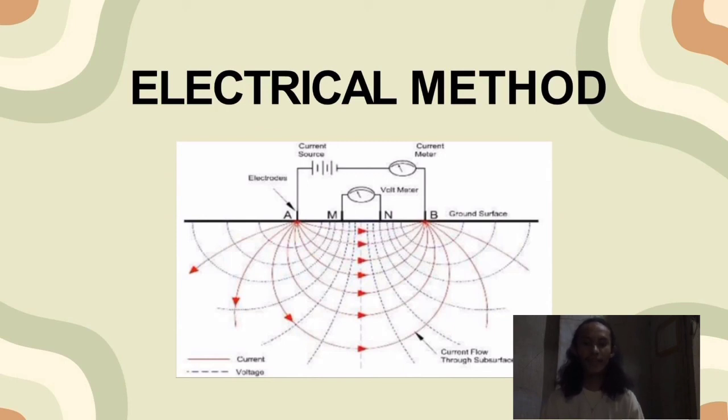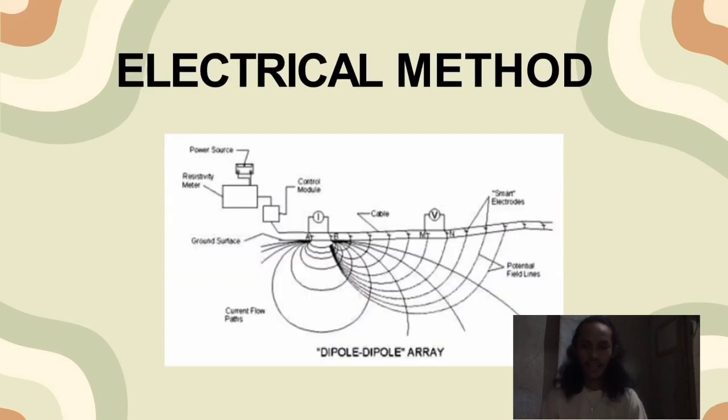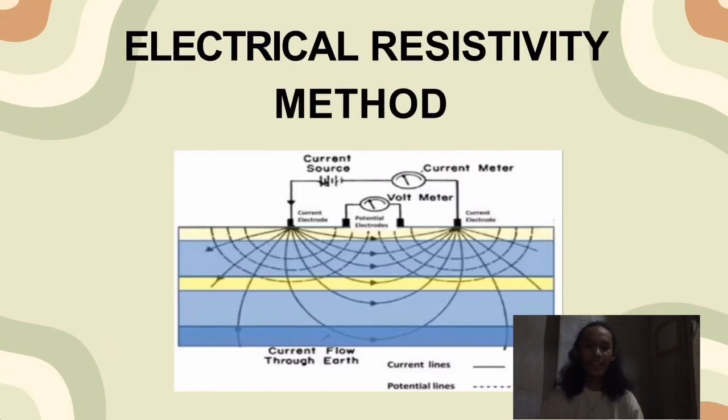Electrical methods are numerous and more versatile. They are more popular because they are successful in dealing with a variety of problems like groundwater studies, subsurface structure, and many others. Controlling properties: in the electromagnetic method, electrical conductivity, magnetic permeability, and dielectric constant of subsurface bodies are the relevant properties.